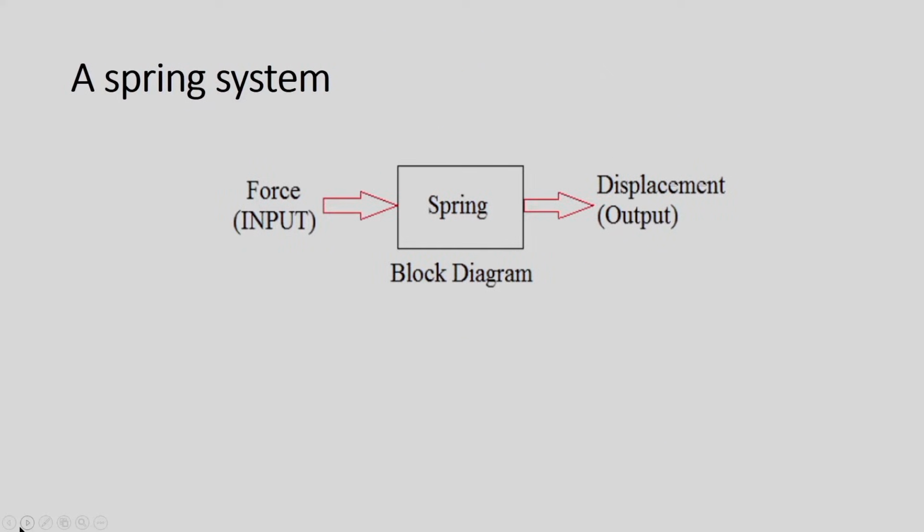The same spring system, the block diagram of a typical spring system can be seen on your screen. As you know, it has a force and it has the displacement, and it follows the principle of operation as F is equal to k into x. This F is equal to k into x would be true in the case of steady state condition.